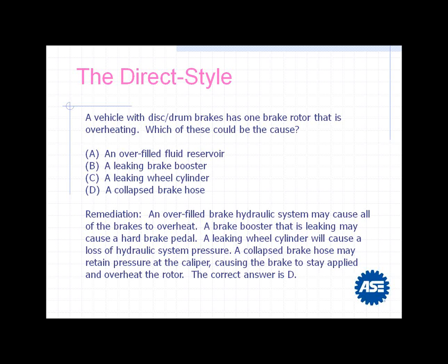If I have an overfilled brake hydraulic system, it may cause all the brakes to overheat. Okay? Remember what I said earlier about analyzing the options based on a single component failure as it relates to an option that's given for a common denominator problem? Okay, I got one brake rotor overheating, and I've given you an option of a common denominator problem, which would be an overfilled fluid reservoir. Okay, take a look at those. That's key to evaluating information in a question. Typically, if we're dealing with a single situation, a common denominator cause isn't going to be your answer.